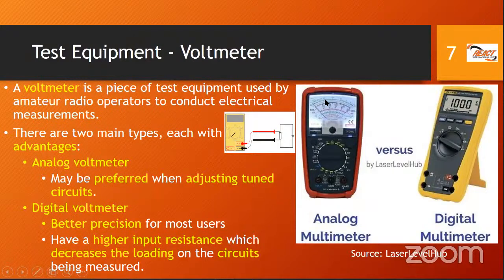The nice thing about it is sometimes you need to see when something twitches. Remember we said when we are doing the plate current, you just want to see when there's a pronounced dip. Sometimes it's harder to tell when something increases or decreases on digital displays like this. But on a display where you have a needle and you see the needle going up, going up, going up, and then all of a sudden it dips down and then goes back up. Sometimes you need to have that visual indicator to know, yes, there was a little dip or a decrease at a point in time.